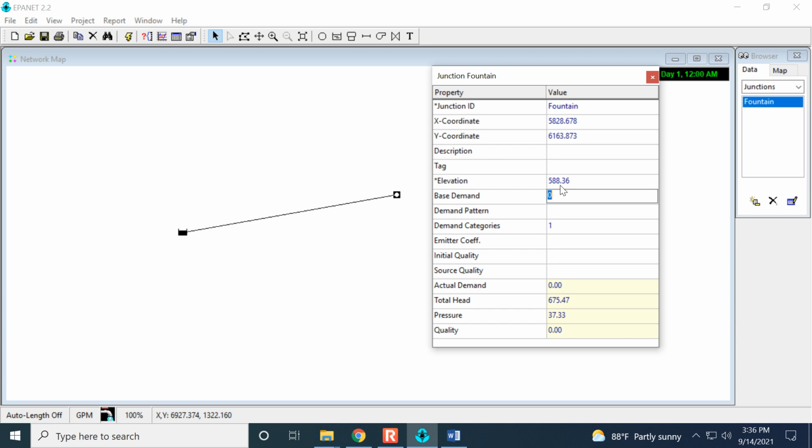So I give you an elevation, a required pressure, and pipe characteristics, and you're trying to determine how high the flow rate can go and still deliver the required pressure. Question 10 is kind of an iterative problem that you can solve by changing the demand and calculating the pressure, over and over again, until you hone in on the maximum flow rate that still gives you 55 psi.